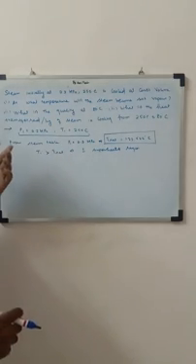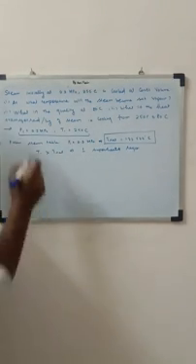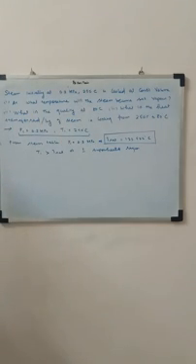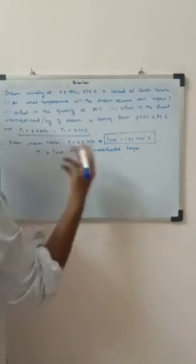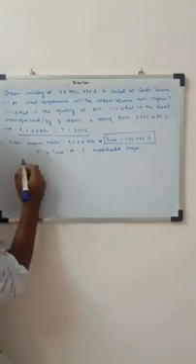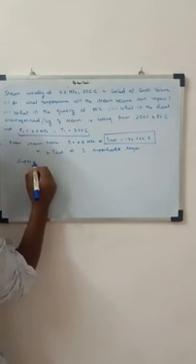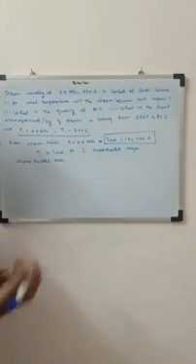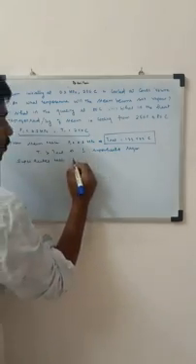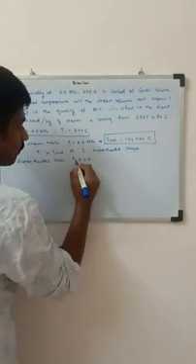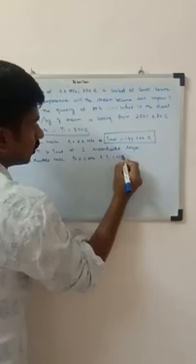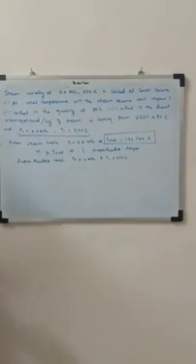So now what is the question? The question is, at what temperature will the steam become saturated vapor? First of all, let us find out what volume it occupies in this state. So let us go to the superheated steam tables. Since this is in the superheated region, we go to the superheated table, and for P1 equal to 0.3 megapascal and T1 equal to 250, what is my volume? That's what I need to find out.